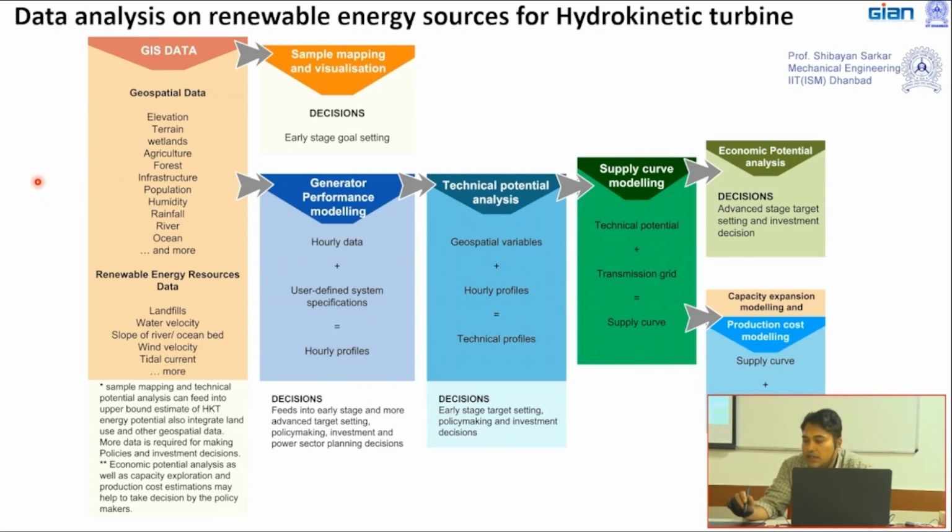Now discharge is available in this particular area. While you are installing a turbine, you need to have some idea of the cross section of this river, because ultimately you require the velocity. You can get that velocity if the cross-section flow area is known to you as well as the total discharge. You divide these two, discharge divided by area, and you get the average velocity through this area, that means through this river or canal.